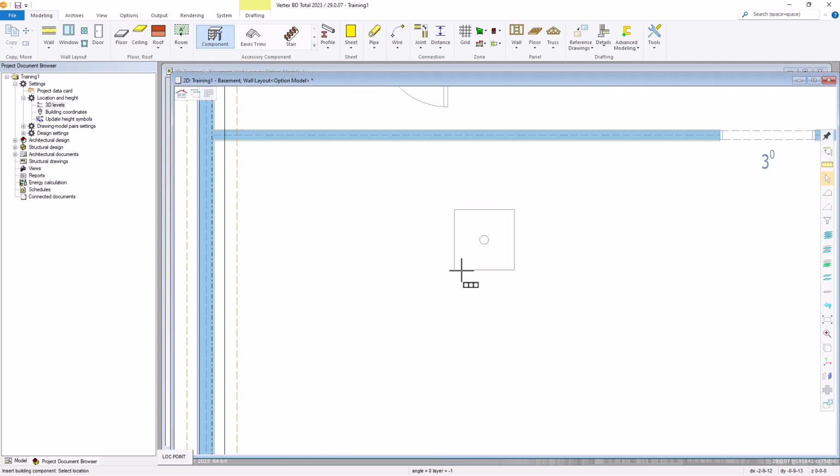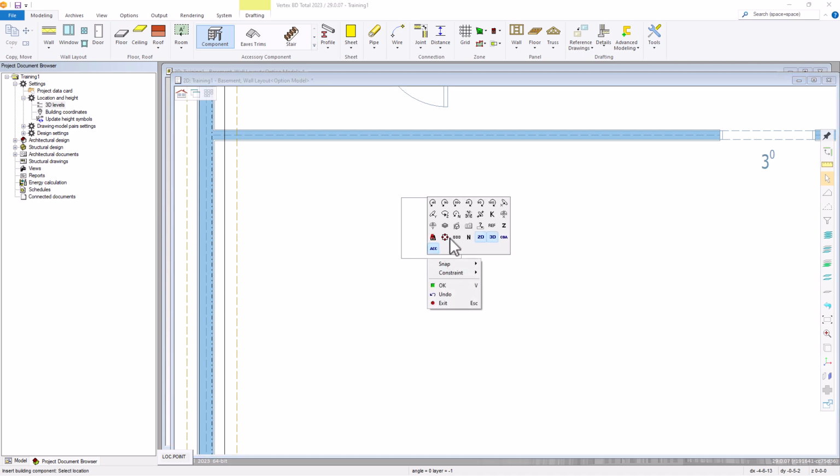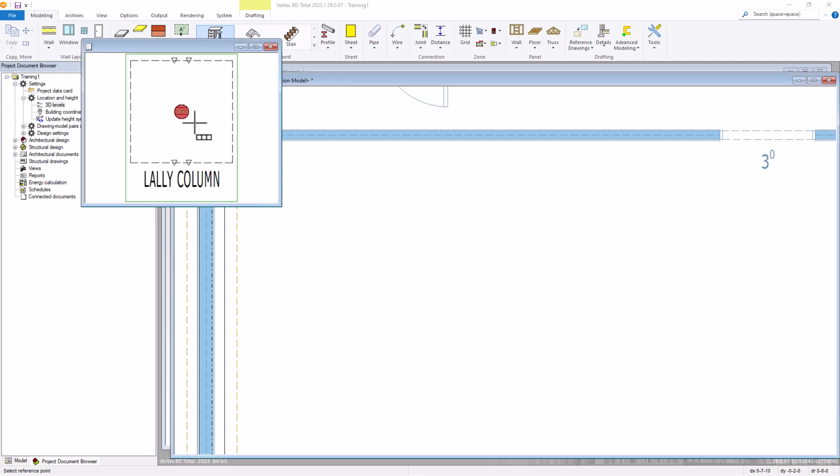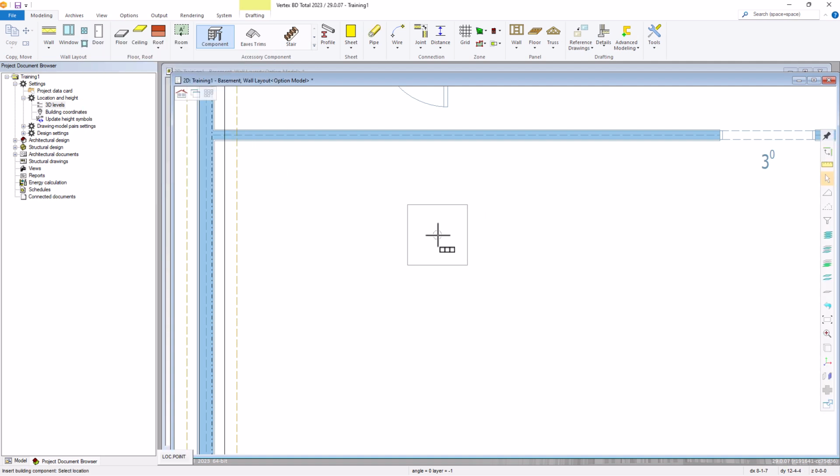And when we zoom in, it's using a reference that's not exactly centered anywhere. Doesn't really make any sense, so we're going to fix that. We're going to right click. We're going to select a reference point. You have all these tools again, similar to what we saw when we were inserting a washer and dryer. You can rotate, scale, modify, but we're going to just set the select reference point. And we're going to zoom in and make sure that we are in the center of this circle. Get that yellow icon, and now that's our reference point.